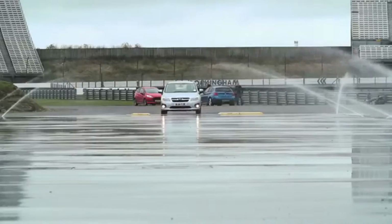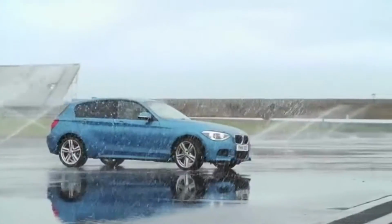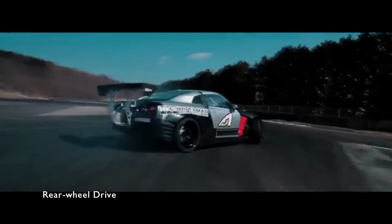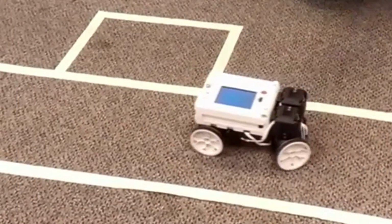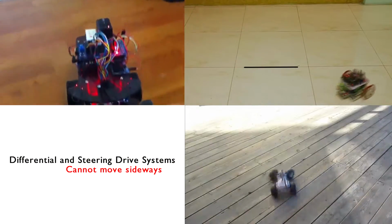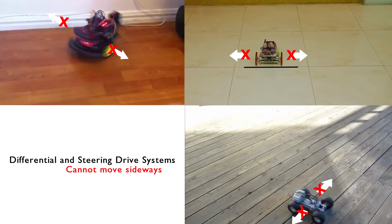Different steering drive vehicles distribute power to the wheels differently, based on their automobile layout. The basic layouts are front-wheel drive, rear-wheel drive, and four-wheel drive. The same layout can be applied to robot as well. One shared characteristic of differential and steering drive systems is that these robots cannot move sideways. So, is it possible to make the robots move in directions other than just forward and backward?